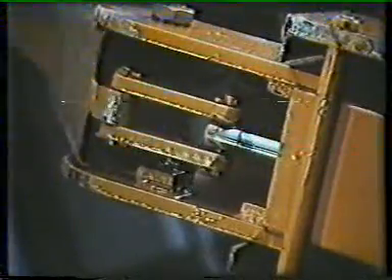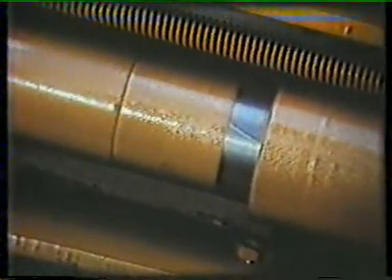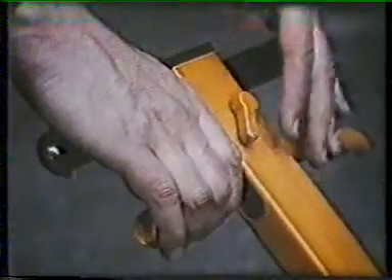The lever is connected to a small piston which pumps oil from the reservoir through the non-return valve. Each forward stroke of the piston injects a small volume of oil through the valve to the ram of the jack. Successive pumps on the piston extend the ram and raise the jack. The oil release valve allows the jack to be returned to its starting position, ready for further use.